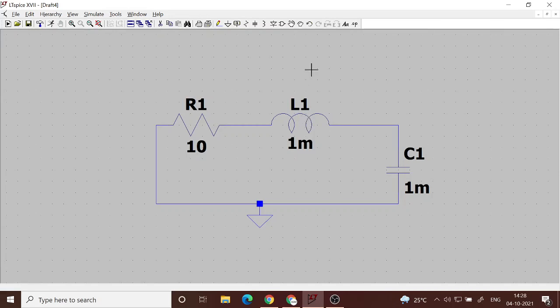So that is the frequency, 159 hertz. Now if I take the inverse, I get a sense of the time period involved. 1 divided by 159 is like 6 milliseconds. So that is one period of the undamped natural frequency that we observed earlier, 6 milliseconds.